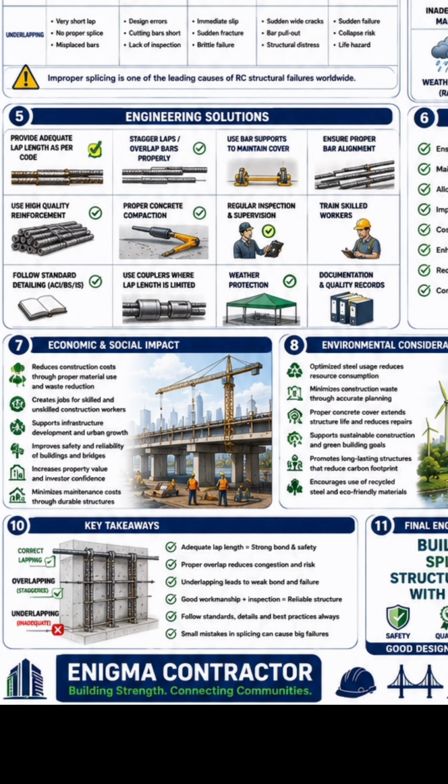Yeah, the next thing is to use couplers where lap length is limited. So where you have limited lap length, it is very, very important you use couplers to join two or more reinforcements, because couplers are designed to help you extend your reinforcement. So whereby maybe the lap length is short, you can just make use of couplers to increase the length of your reinforcement, because the couplers are also carrying the strength of the reinforcement.